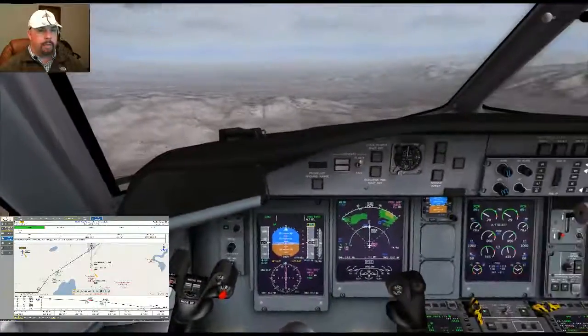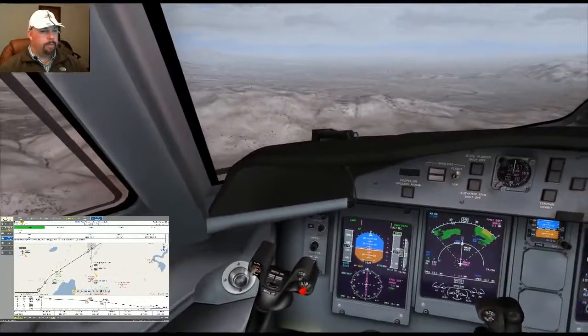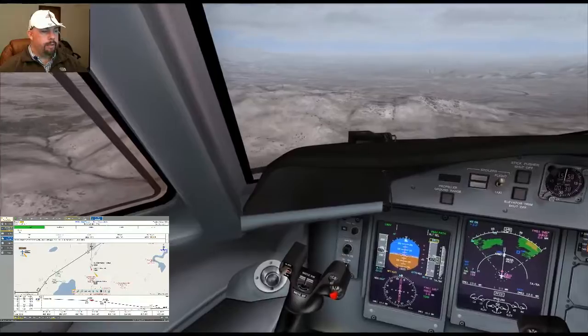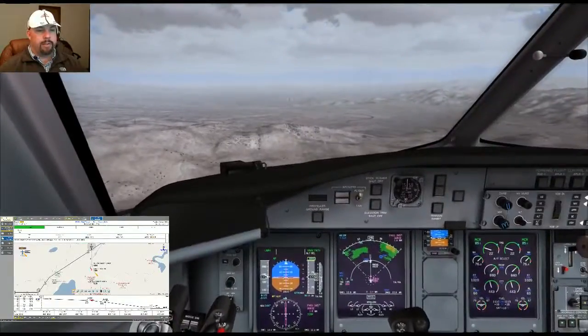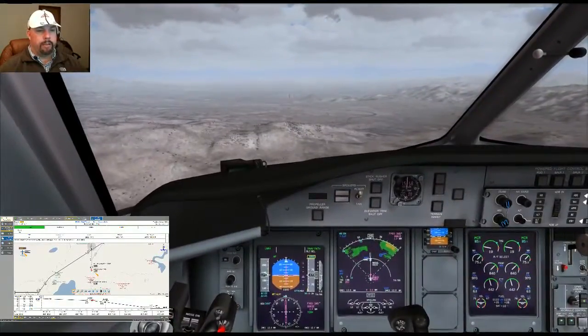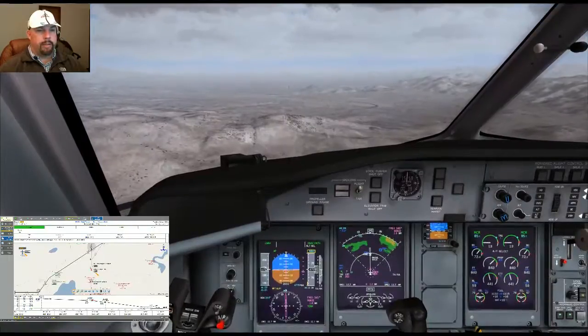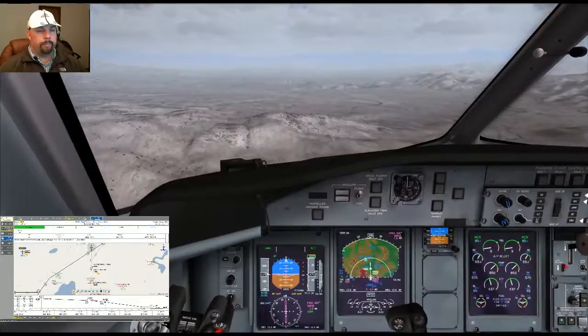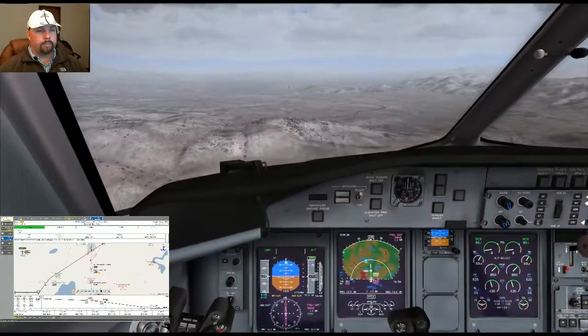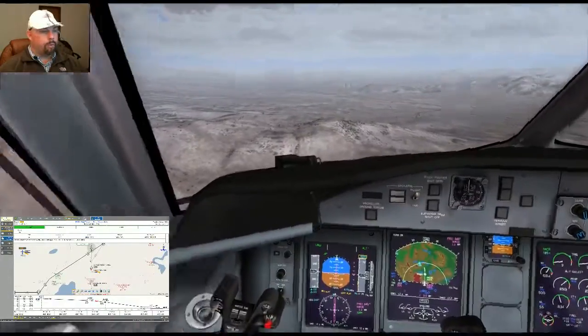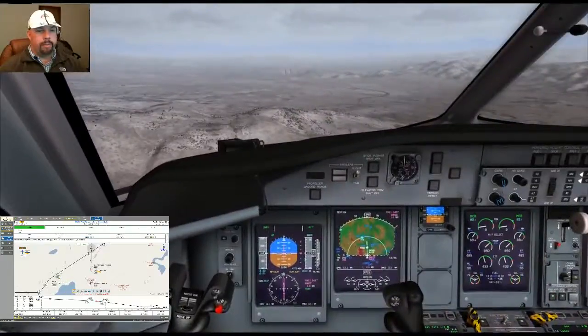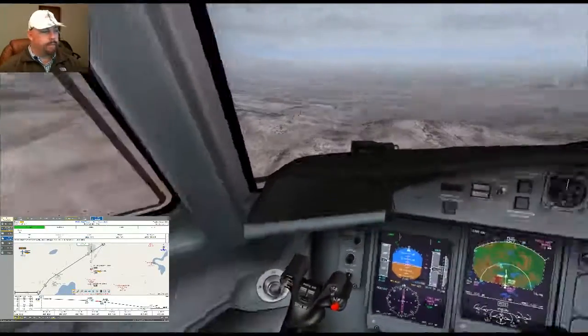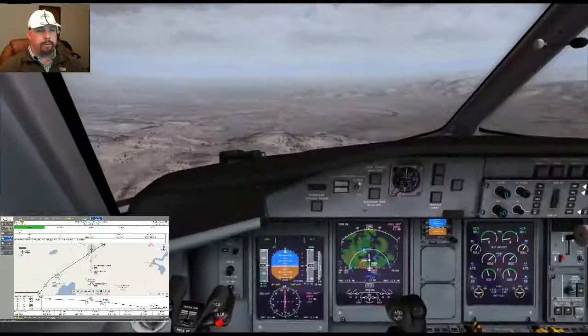Okay, about 9 miles out now from the runway, on our way down to 6,800 feet for Gucky. Gucky's about 7 miles out, so we'll start to configure the plane for landing as we pass Gucky. We're right where we should be in terms of altitude here, on our way down to 6,800 feet for Gucky, according to the chart, so we're good.